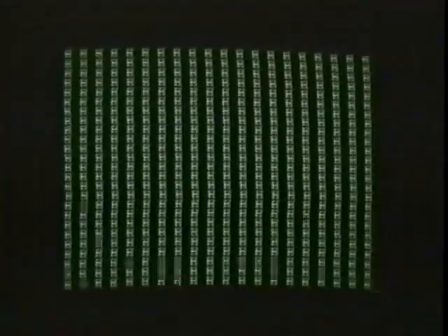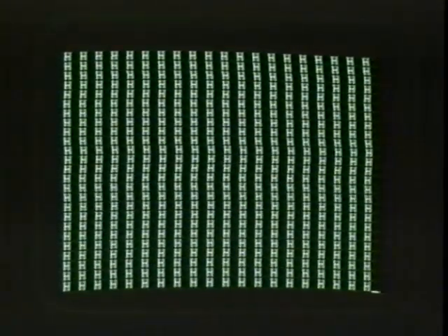Before completing the sweep adjustments, turn the monitor on and off several times and check for a stable display. Also, make sure that the alignment is good both when the unit is cold and warm. It is possible to set the sweep adjustments just within the capture range of the oscillators, which will cause the monitor to sync properly at times and to roll or jitter at others.